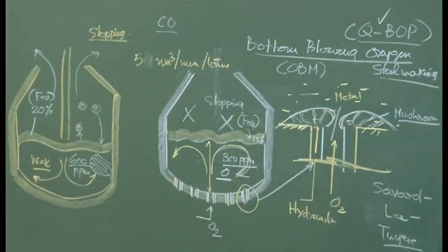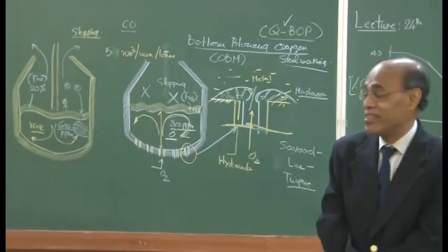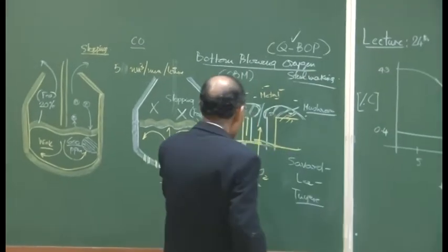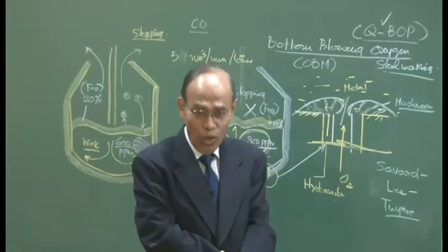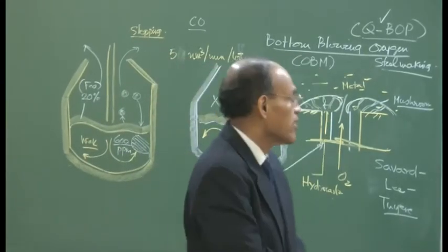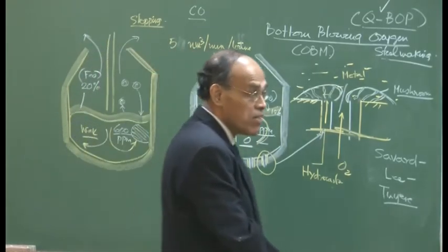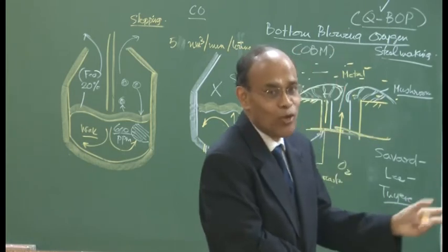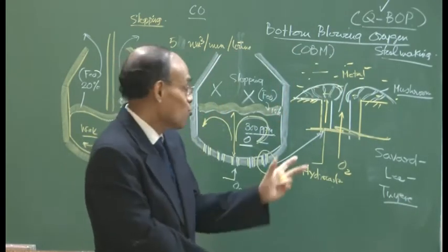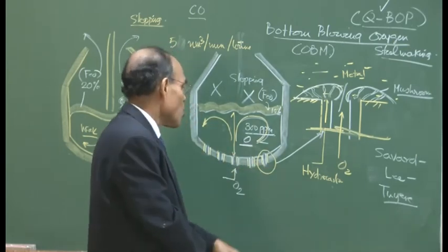And most importantly, you tend to generate more hydrogen in steel, and hydrogen is extremely dangerous. Where does hydrogen come from? Because you are putting in hydrocarbon as a gas, cracking takes place, and hydrogen has good solubility in steel. At 1600 degrees centigrade with 1 atmosphere partial pressure of pure hydrogen, the solubility of hydrogen is 28 ppm. Of course, it is not pure hydrogen, but you can expect 2, 4, 5 ppm hydrogen. In this particular case, it is not so unlikely.